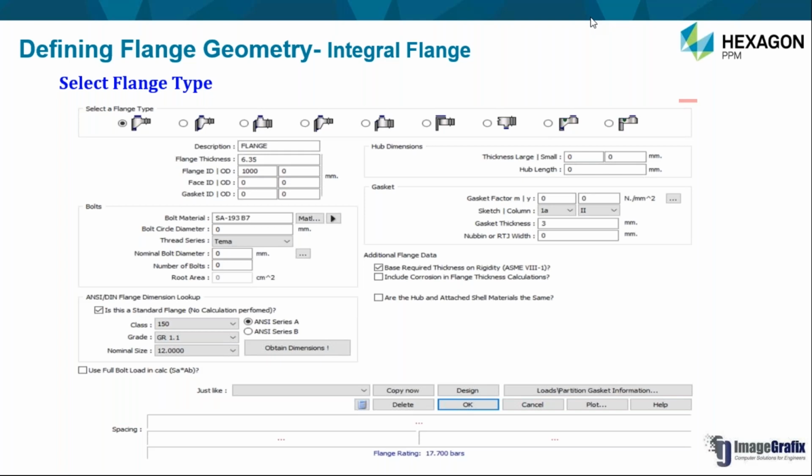The flange thickness at the lower end of its hub, that is G0, we usually start the design assuming it is similar to your shell thickness. So let's say we have the value of G0 and the ID of the flange. These are the two fixed parameters, so we always have to start from them. As flange design is an iterative method, we also have to assume the flange thickness, and then make sure that whatever flange thickness we have selected is safe or not. Fine, so let's start.